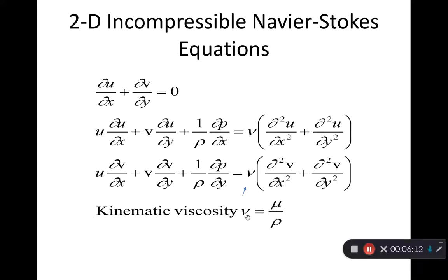Here we have introduced a new quantity called nu, which is our original viscosity, molecular viscosity, which has got an interpretation of what the molecules are doing, divided by rho. We call it a kinematic viscosity because its dimensions are velocity times distance. Velocity and distance are kinematic quantities. It does not have anything like a mass or anything like that, so it's not a kinetic quantity. So nu has got the dimensions of meter square per second or feet square per second. So this is called the kinematic viscosity.